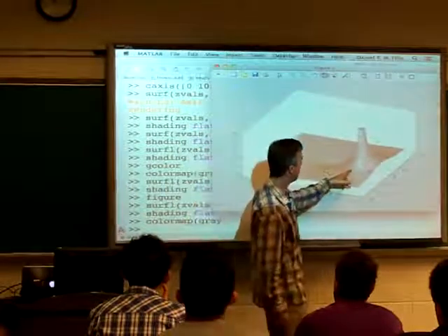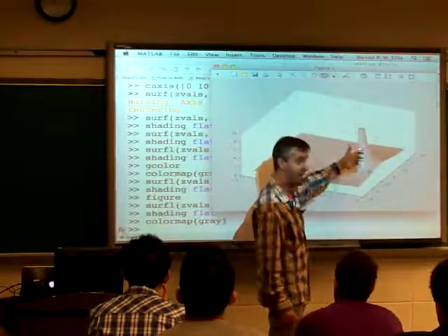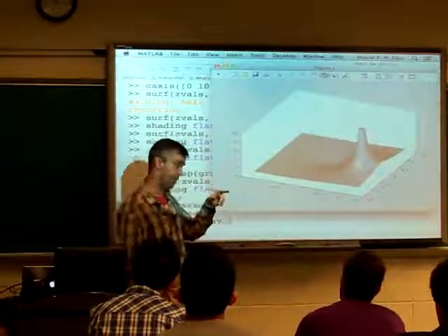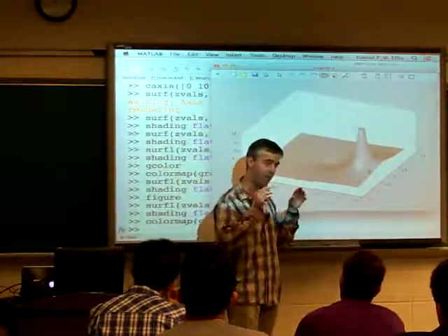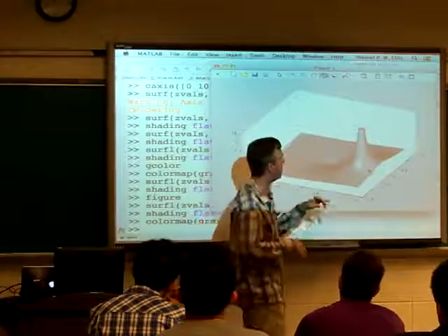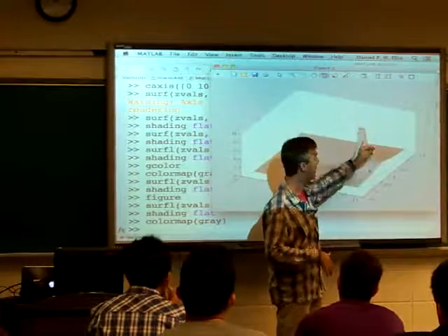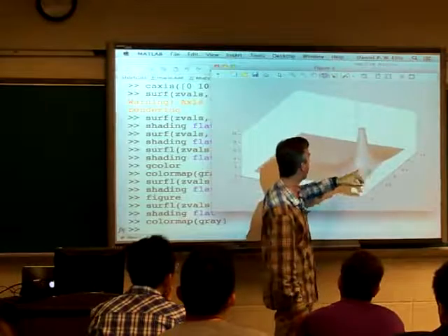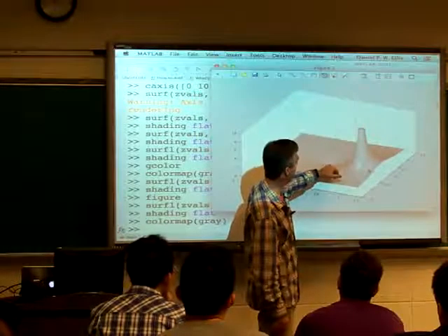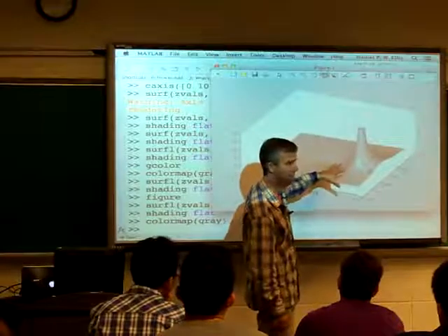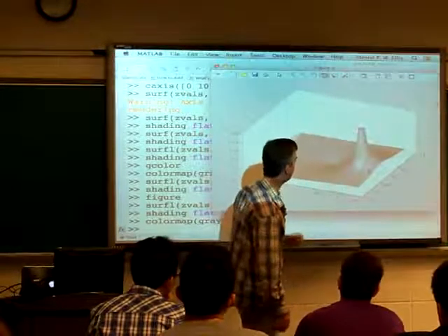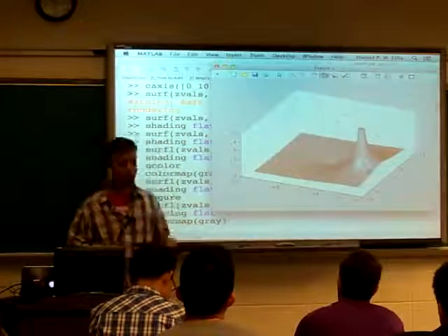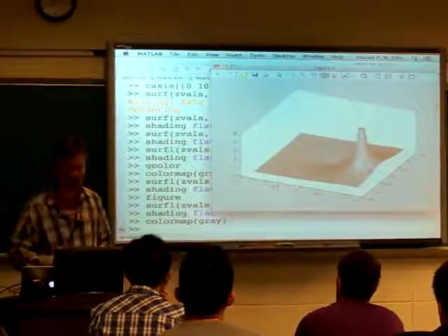And what we see here is that there's this thing sticking up, looks kind of like a tent with a tent pole in it. That's the pole, right? This expression, 1 over 1 minus lambda z to the minus 1, has the denominator going to 0 when z equals lambda. So this is a root of the denominator, so it's a pole where the magnitude of the closed form expression goes to infinity. There's a 0 here. It turns out that when z is 0, that whole thing goes to 0. So that's kind of like a not very interesting 0. The zeros at the origin at z equals 0 are not as interesting as the zeros elsewhere, let's put it like that.